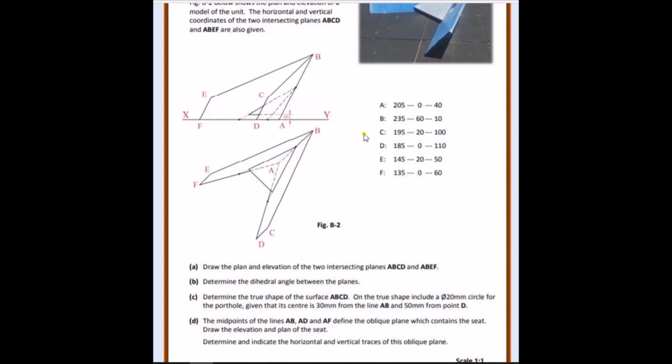Draw the plan of the cone: from A here, draw an arc out to the side, bring a level line across, then from B in elevation draw this cone again. This gives you the true length of the side of the cone. If you bisect that line, it's a matter of bringing this point straight in. That allows you to find this point. Then we just construct your 2 lines, up 5 mils, a line across here for the seat.